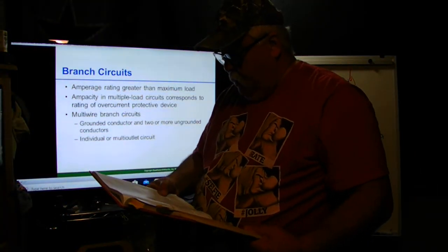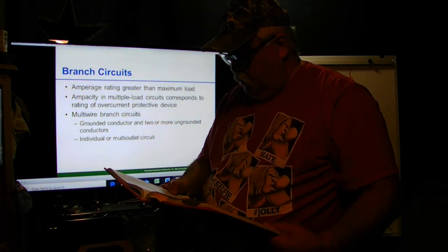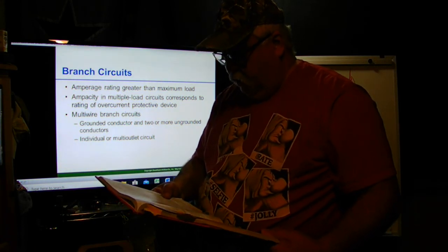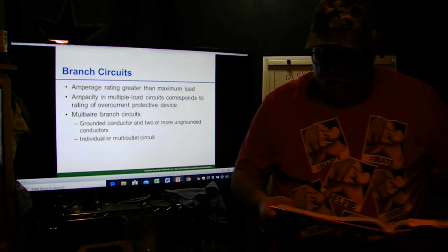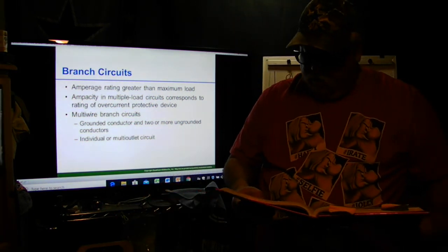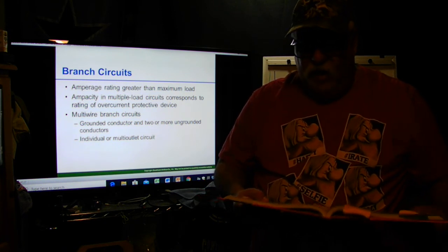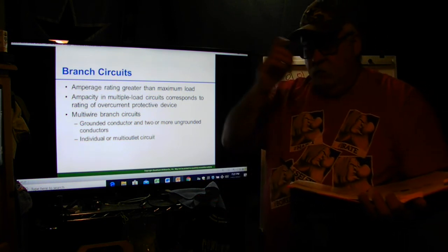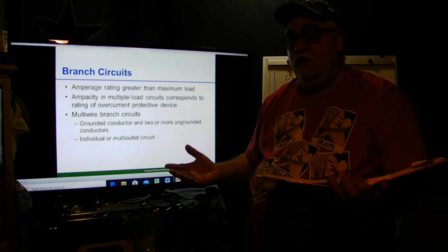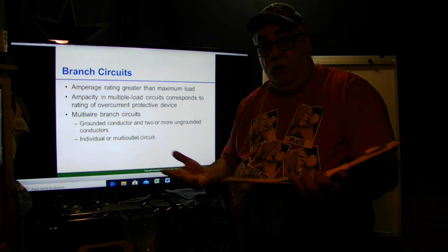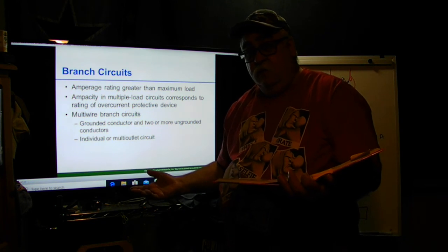Forgot on that part. It says the conductor is acceptable. However, for circuit supply and hardwired devices such as electric heaters, air conditioning units, and water heaters, the fuse or circuit breakers can be rated at the next rating. What does that mean? I got a motor that's using 15 amps. All I need is a 14 gauge wire.